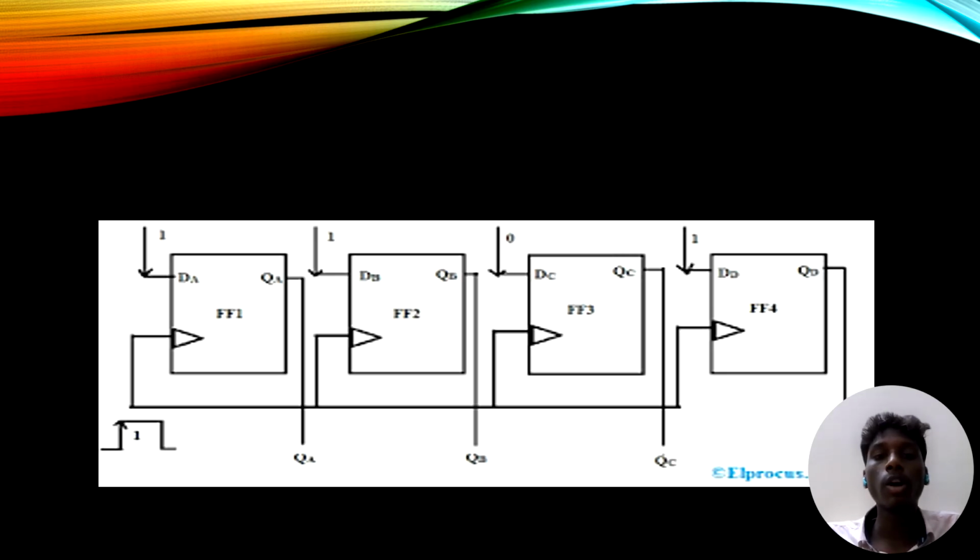The working principle of the circuit is that the PIPO register allows data to be loaded in parallel and read out in parallel. When a clock pulse is applied, all four flip-flops store their respective input bits at the same time. The data on the input lines DA, DB, DC, DD are transferred to the outputs QA, QB, QC, QD in a single clock cycle.